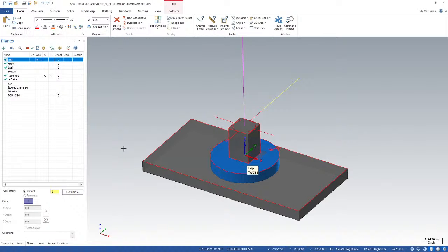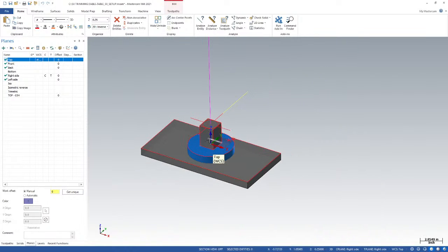Because we could have, for example, a machine with a really long bed, and we could have 3 of these parts set up side by side. And really, we can machine that with the same program, only calling a new work offset for each location that we're machining at.